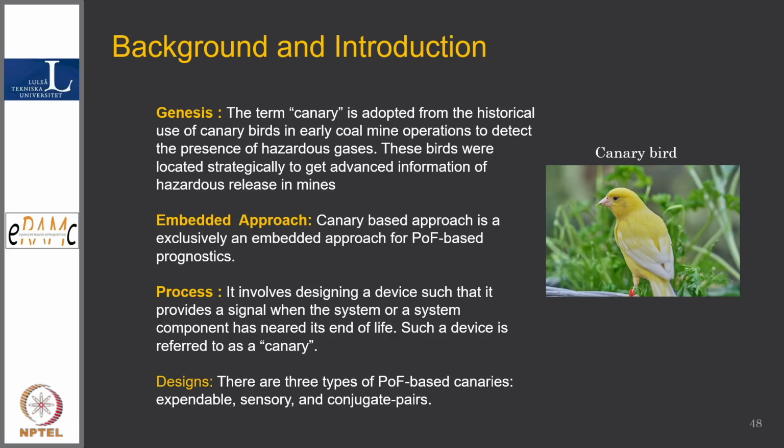So what I do is create a weak link, physically a weak link, so that if the assembly that I am lifting falls, it's okay, but it gets snapped from the main system, so that it doesn't damage my main system. So these kinds of settings are provided on the main lifting system, where the hydraulic pressure is set in such a way that if the load goes beyond a certain limit, the system cuts off, number one, and number two, the weak assembly will also fall into a safe place. I mean, it will not be a hazard to others.